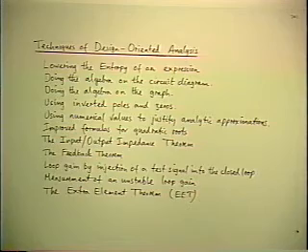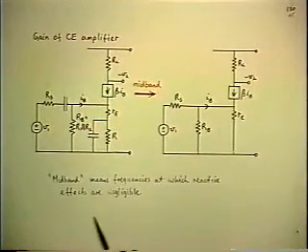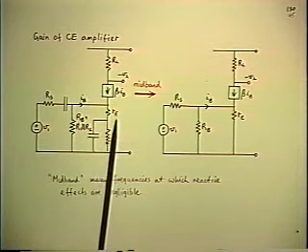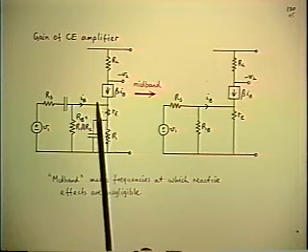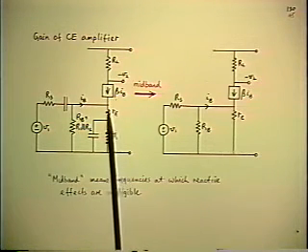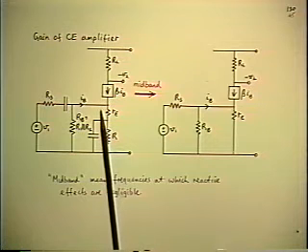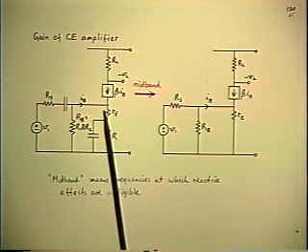And the example is the one that I showed briefly already. Taking one step further back at the moment, the circuit we're talking about is the basic common emitter bipolar transistor, so-called linear amplifier stage. The picture on the left shows the equivalent circuit model of the transistor, the beta collector current generator, the RE base emitter junction slope resistance.